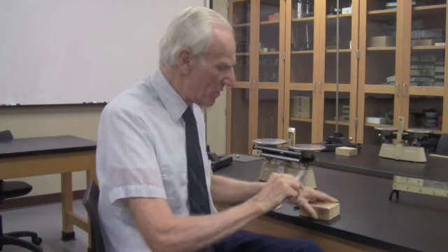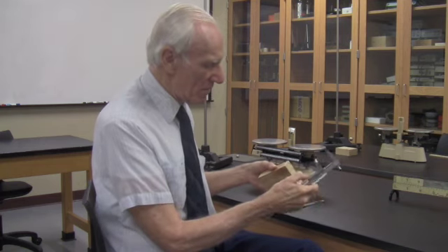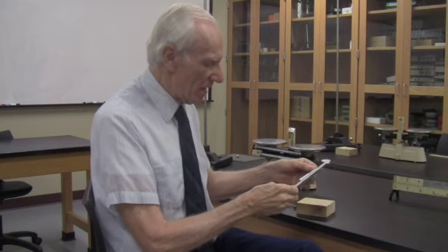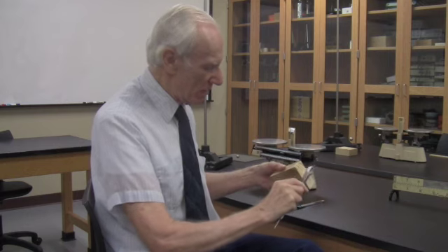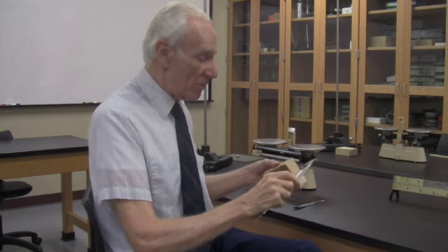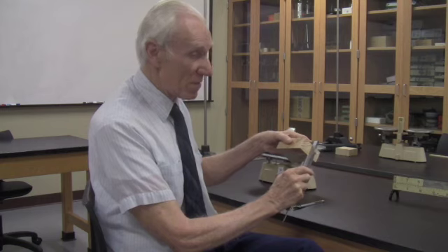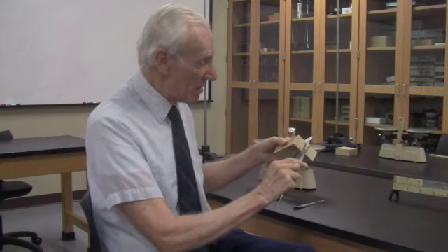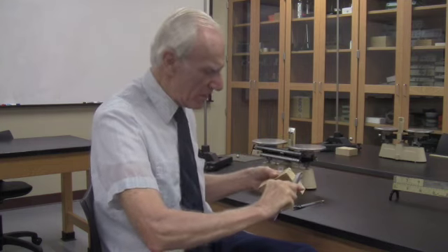So let me put this block in, and this is the way you do it. This has got a little thumb adjuster here, and when you let up on it, it kind of locks that in position. When you push into it, it allows this to move. And so one can let up on it and take it off and read it, but if you do that, it's pretty clear that your reading is going to be a little bit on the high side. Since this can measure to 0.02 of a millimeter, you want to keep tension on that and read it while it's under tension.